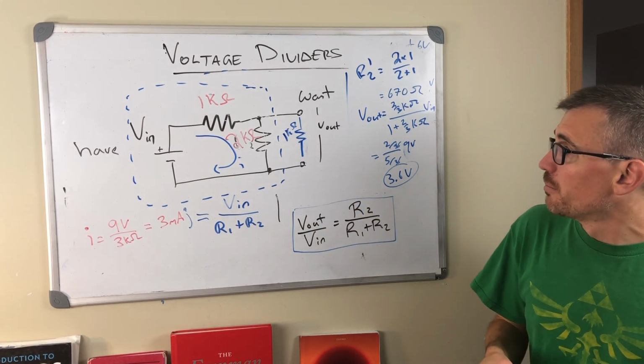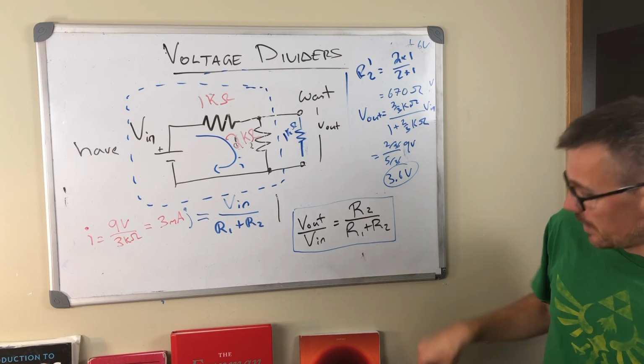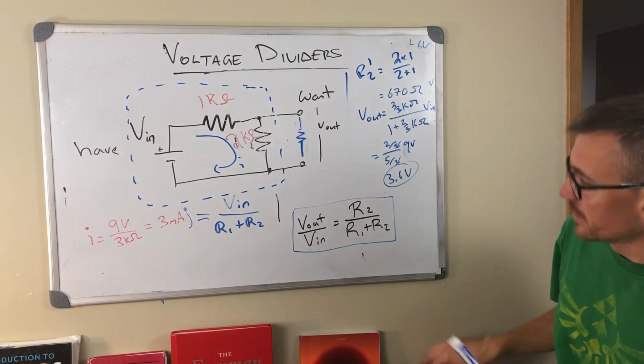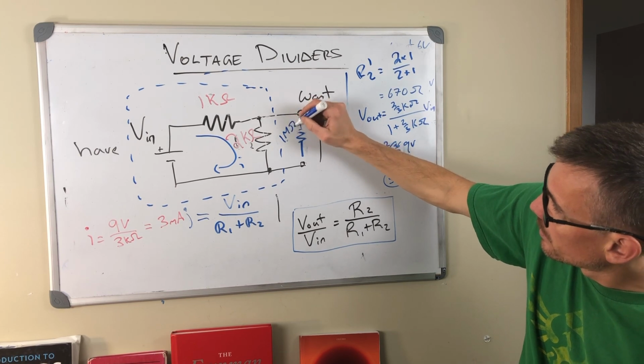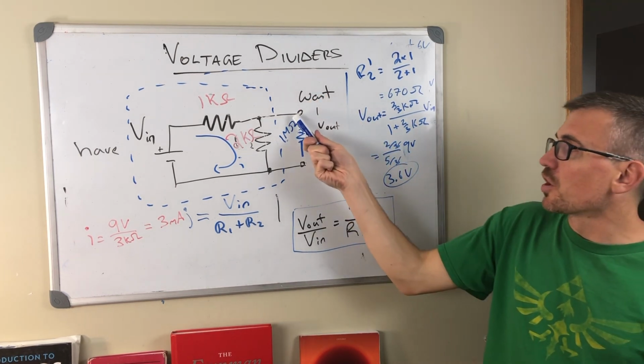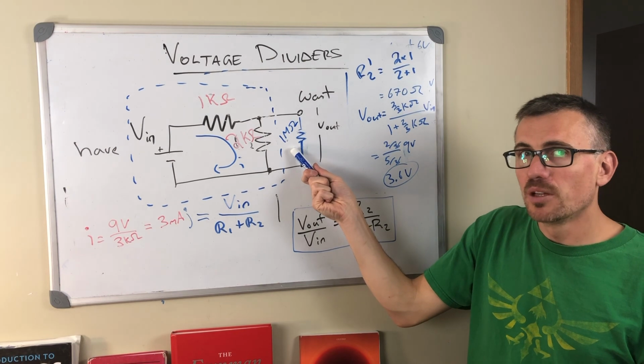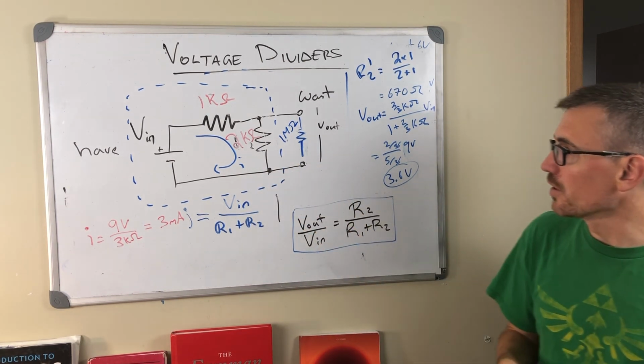But if I did a different example, if I plugged in a different device that say had a mega ohm or a giga ohm, let's just say a mega ohm, I now have a parallel combination of a mega ohm and 2 kilo ohms.